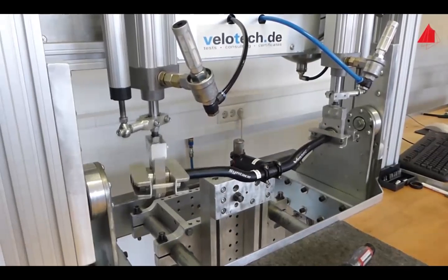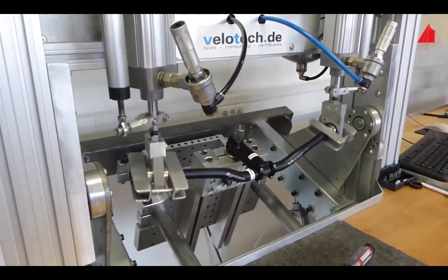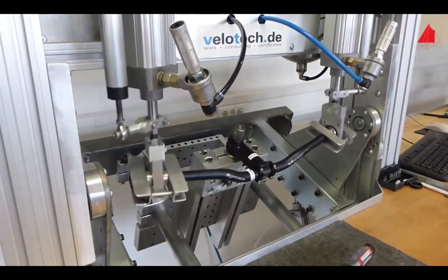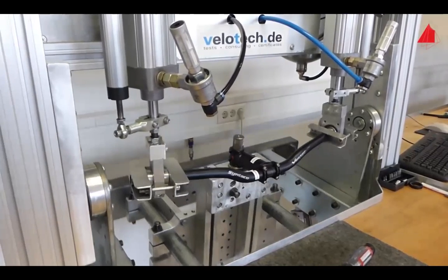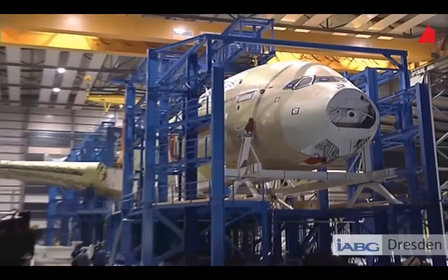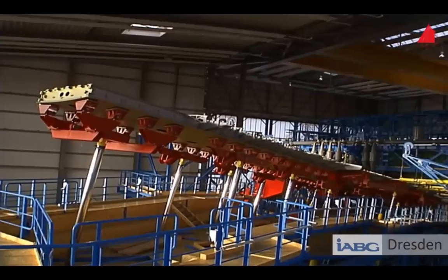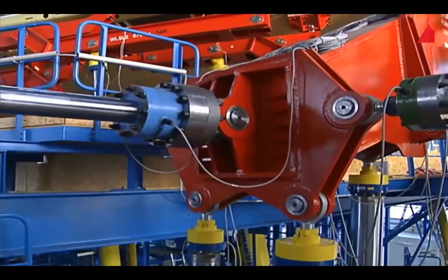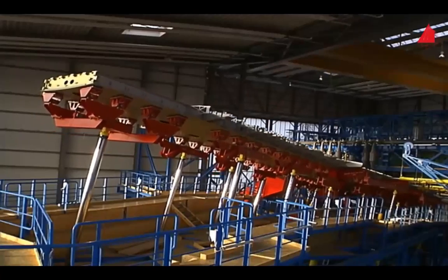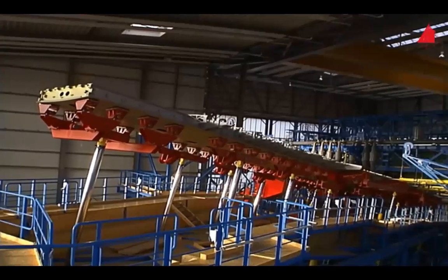Moreover, the fatigue strength does not only depend on the material. The mean stress has an important influence, the shape, the surface quality, environmental conditions, and much more. Not an easy story. Before an aircraft is allowed to take off for the first time, it has to go through extensive stress tests. The wings and many other elements are cyclically loaded in large test rigs. This later ensures the safe operation of the aircraft.